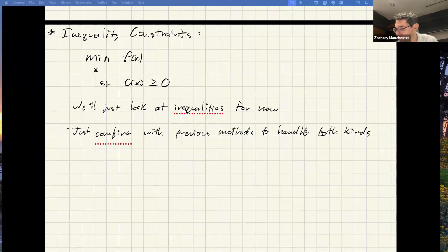And as we said, right, generally for us doing control stuff, equalities are usually dynamics constraints. They can also be something like a goal constraint, like you have to get to this state at the end of the trajectory horizon or something like that. Inequalities are usually things like torque limits, actuator limits, thrust limits, stuff like that, right?